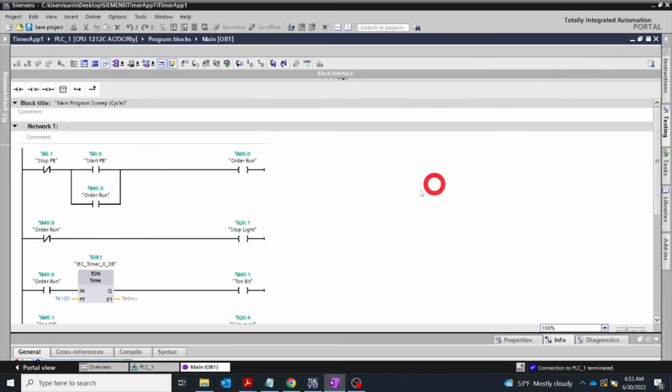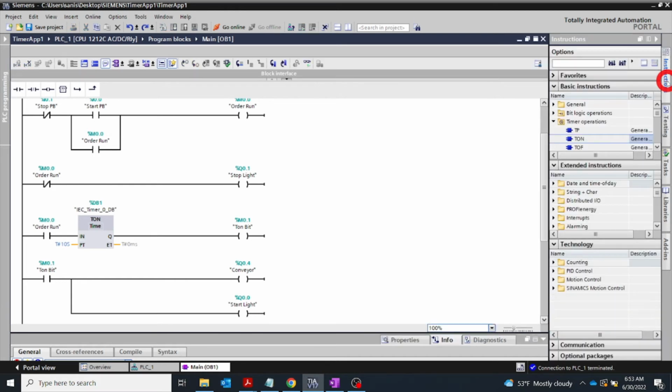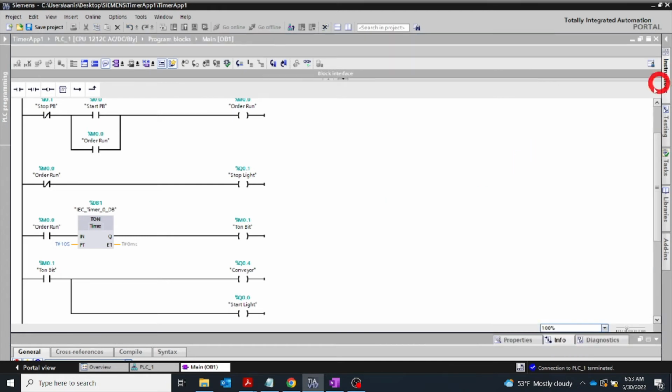Okay, I actually follow the same thing. Again, this one controls the overrun, which I showed you how you could make. This timer we talked about in the PLC timer video, how you could bring that. It is here. You go to the instruction and drag and drop this T on there. Okay, so you should be fine with this. This is another internal bit which we call the T on bit. It is M0.1. So you know how you could make that. I already explained it to you.